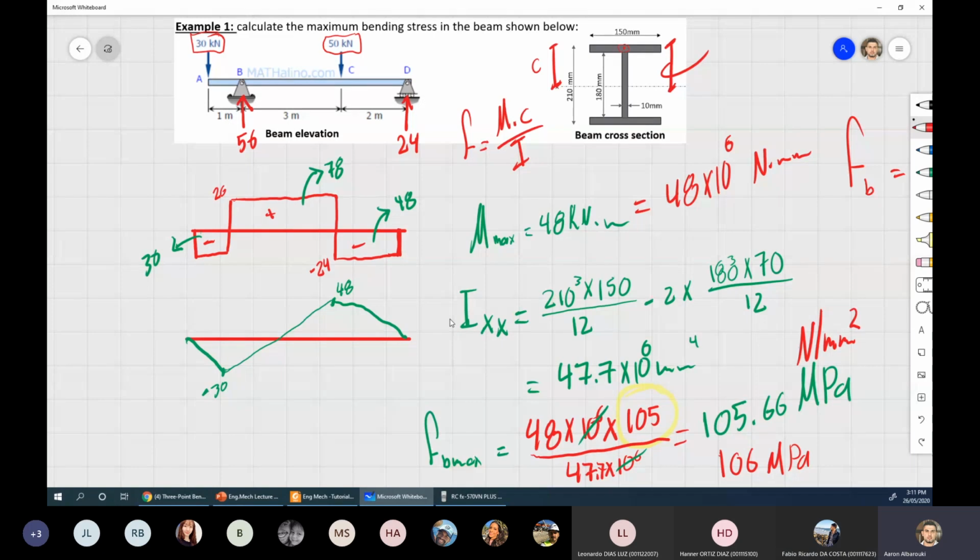So we talked about this previously when we talked about slender members, and two force members. You saw it when we push on a long, thin member, that member will straight away buckle away, will bend laterally, try to escape the load.